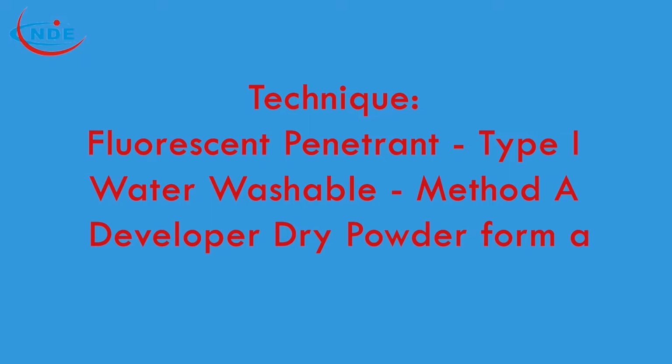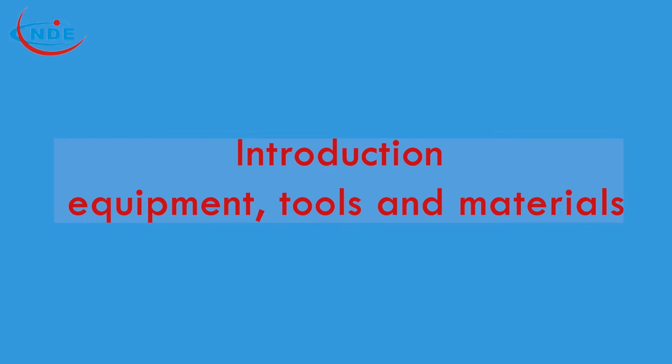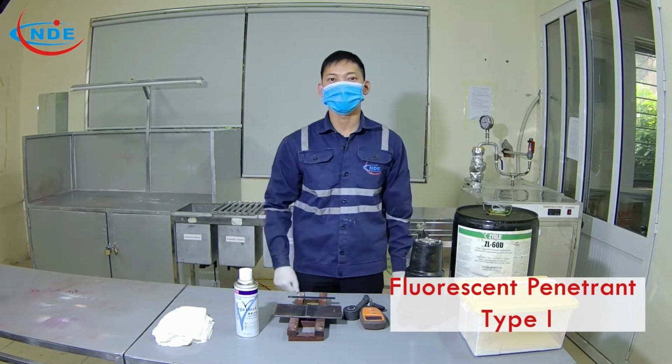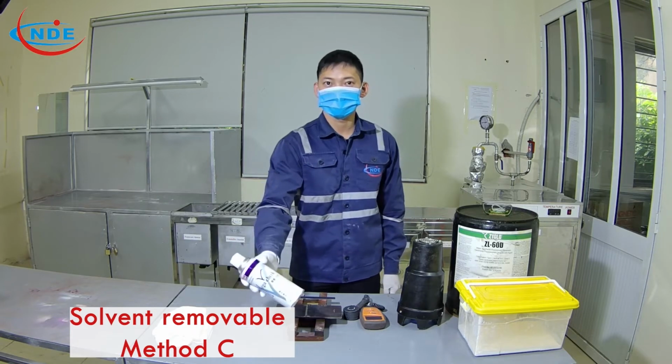The second PT technique introduced to you is fluorescent penetrant examination, Method A water washable, and developer Form A dry powder. There is equipment, tools, and materials necessary for practicing the technique. Type 1 fluorescent penetrant. Method C solvent removable spray bottle.